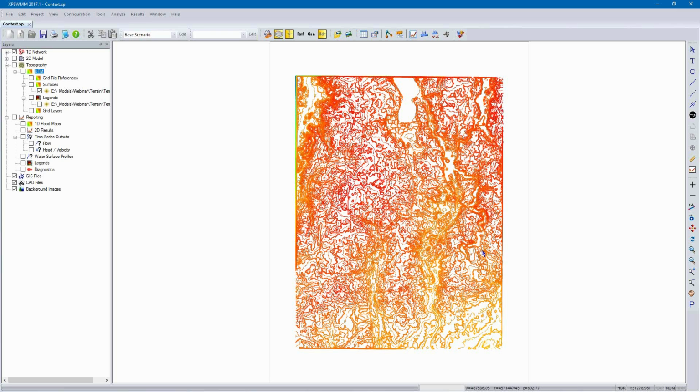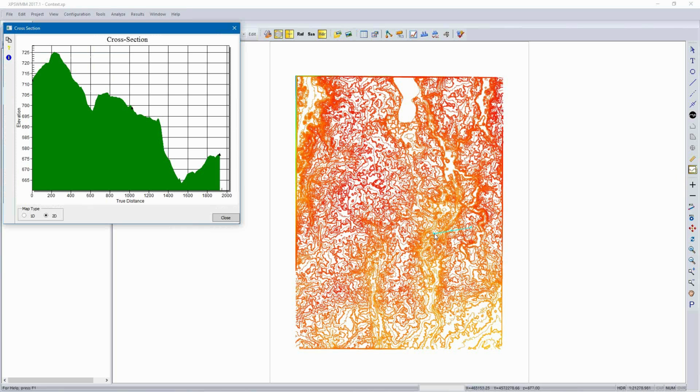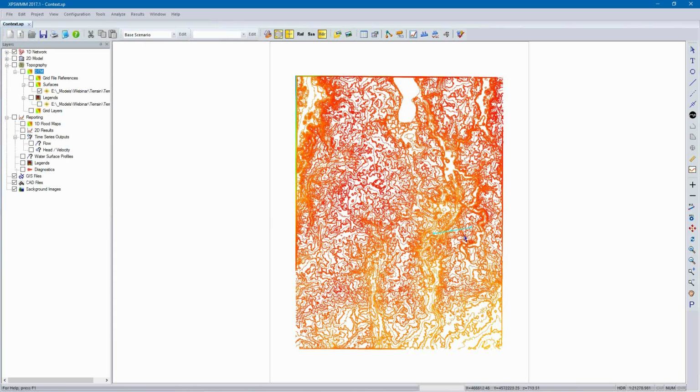So this elevation information can help us populate nodes. It can help us build a two-dimensional flood model. It can help us edit pipes. It can help cut cross sections. We can use the cross-section tool here and look at what that system looks like. And sure enough, I've got a lot of elevation available. Okay, click off that. All right, my project is in this location.